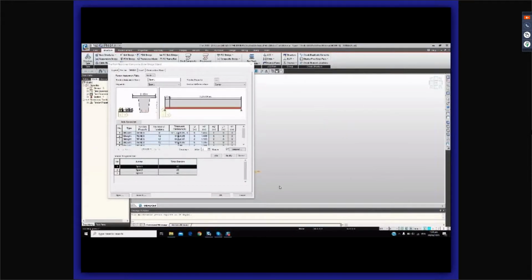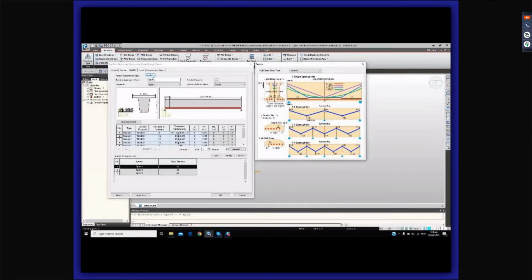So let's now proceed to the next tab, which is the tendon tab. If you click on the guide for the tendon tab, you can see here the different shapes for multiple span girder types. First, we have the harp one. So here are tendons on the elevation view of your bridge, then for the two, and then for the curve. The curve shape is parabolic. Since we will be only using the straight shape, here's the straight shape, the red drawings.